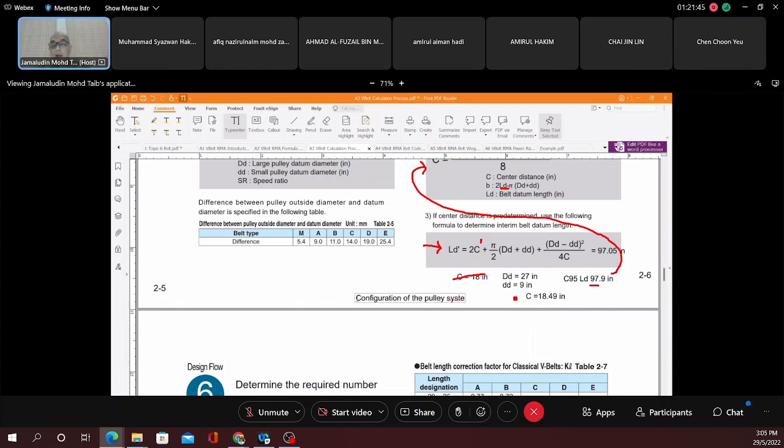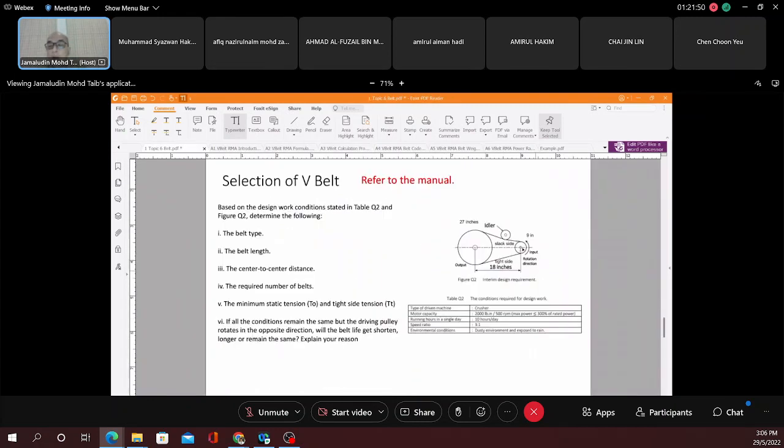What is going to be the diameter of the larger pulley here? The 18 was your initial proposal, but you cannot have that because the belt length is fixed. If the question says a minimum of 18, you choose the larger one. If the question asks for a maximum of 18, you have to choose the smaller one, because the answer should be lower, 17 or 16 and below. That's the idea.